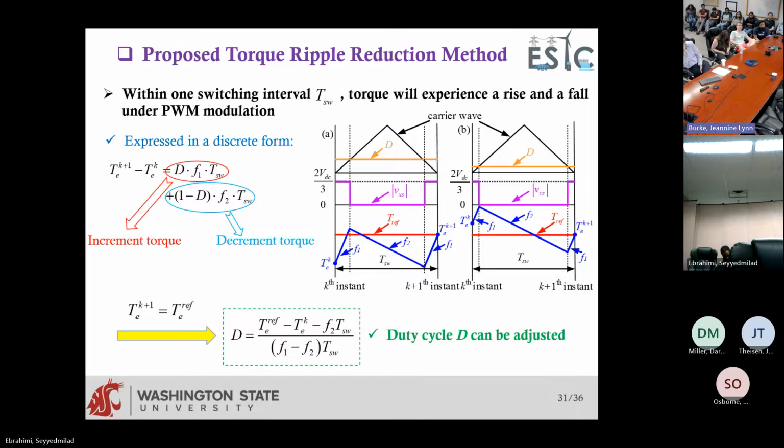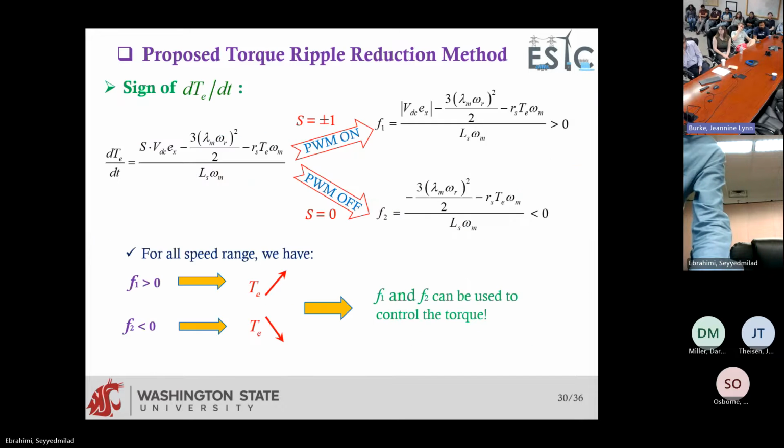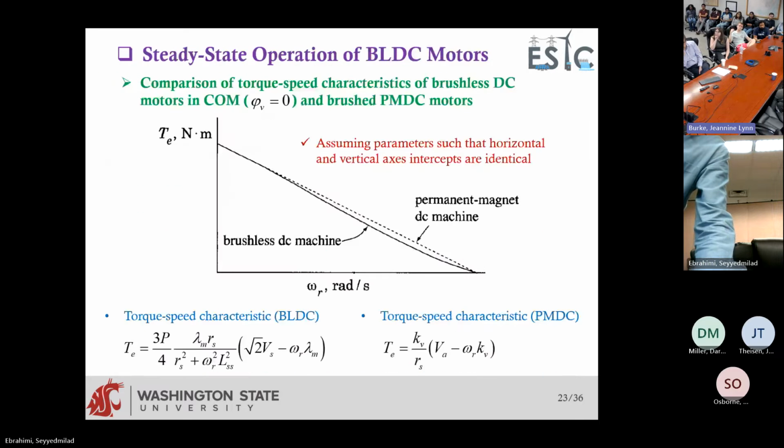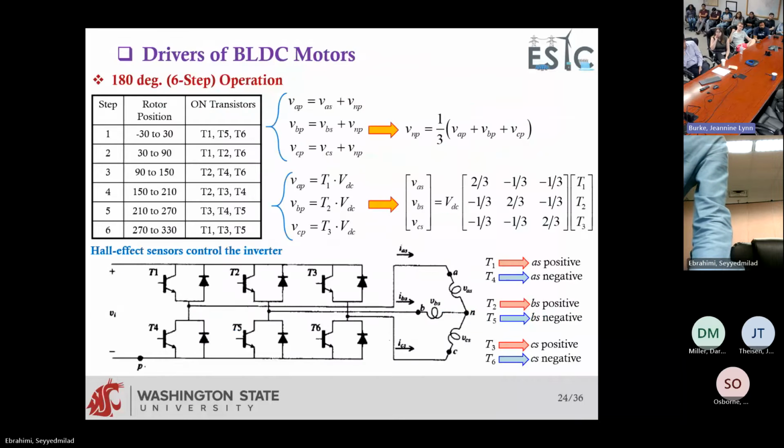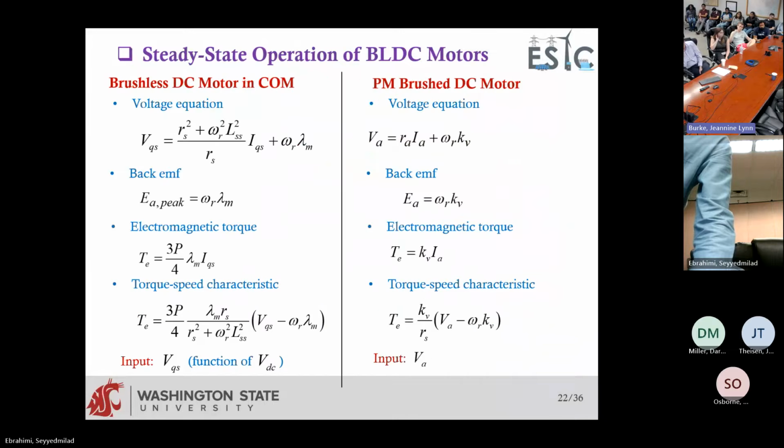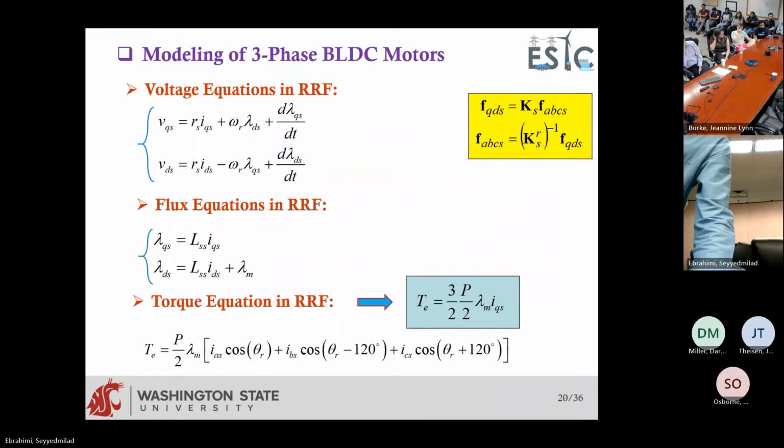Thank you so much. And regarding that, the source in the torque ripple is the ripple in the current, and the cause for the current ripple, the primary cause, is the imperfect sinusoid created by our switching circuit, or is it something else? Let me explain it based on this. This is the model of the machine.